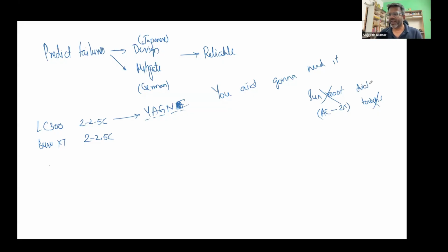Have dials. And let's say that every day you use the dials 5 times. Suppose you're driving the vehicle every day and you use the dials 5 times, then they will design a dial which can do that 5 times every single day for 20 years. So this is the cycle life they will look for when they're purchasing a knob. You have a switch, 20,000 times it has to work. Everything is being designed for a 20 or 30 year lifespan.